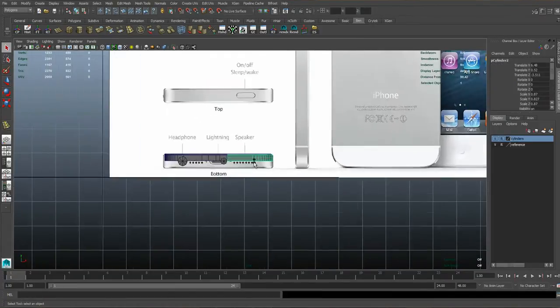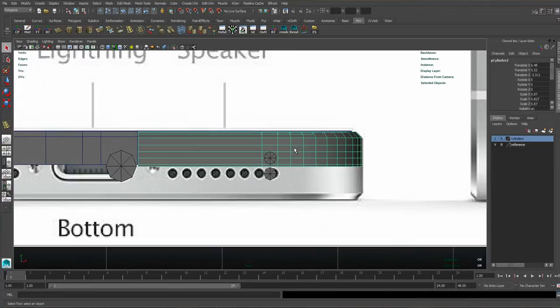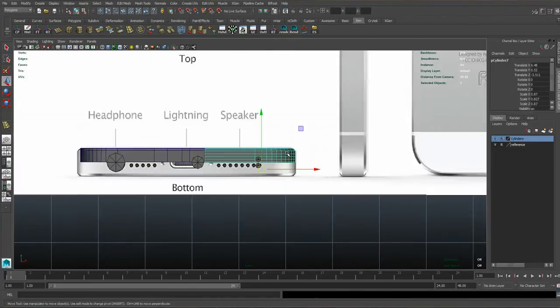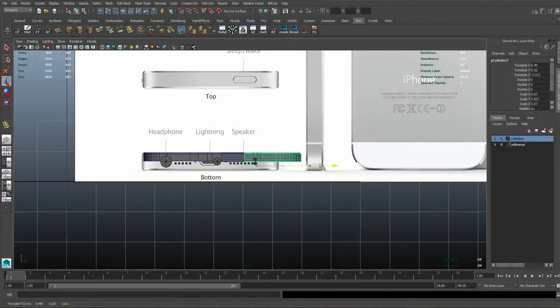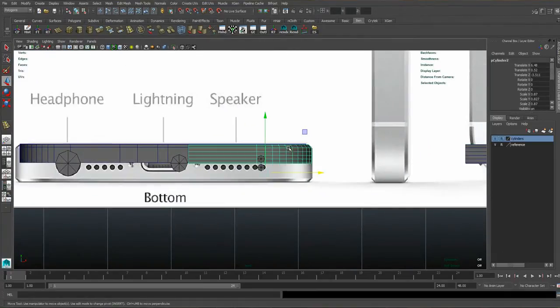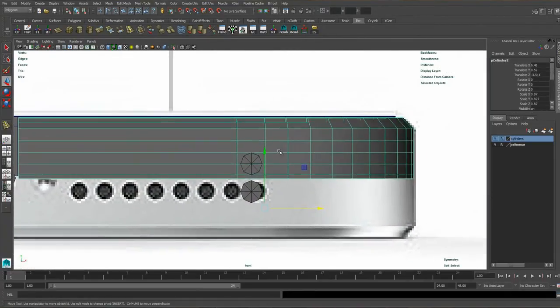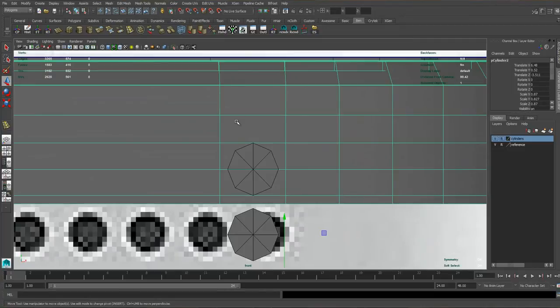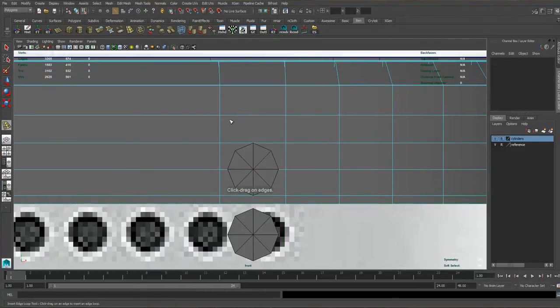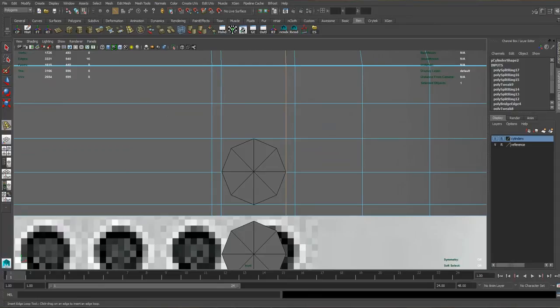And what we're going to do next might be a bit destructive, so I'm going to duplicate the outer part of the phone, just move it to the right a bit and out of the way, just in case something goes wrong. Now what I'll do is add 2 more vertical edge loops here, just to mark out the right hand side. It's important that you do have something that looks like this, so you do have these faces here before you get to these ones here, okay?